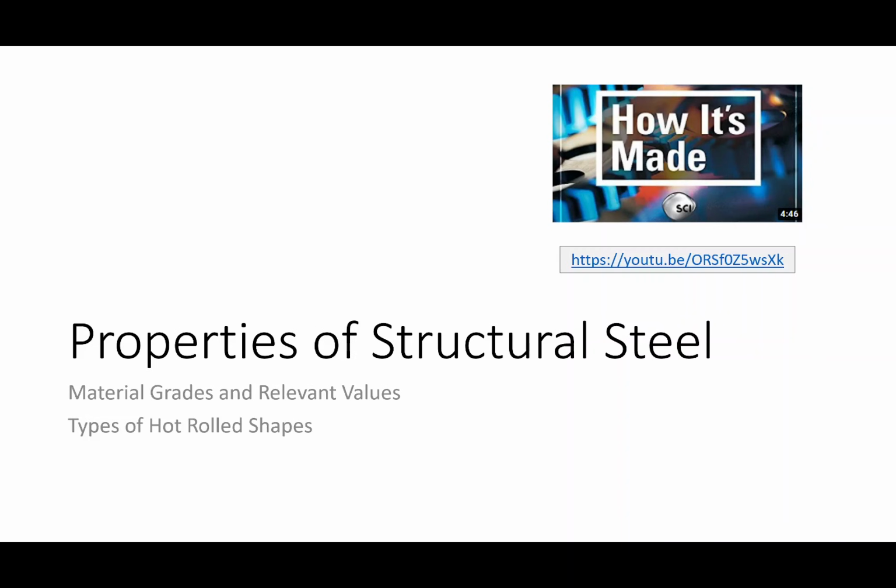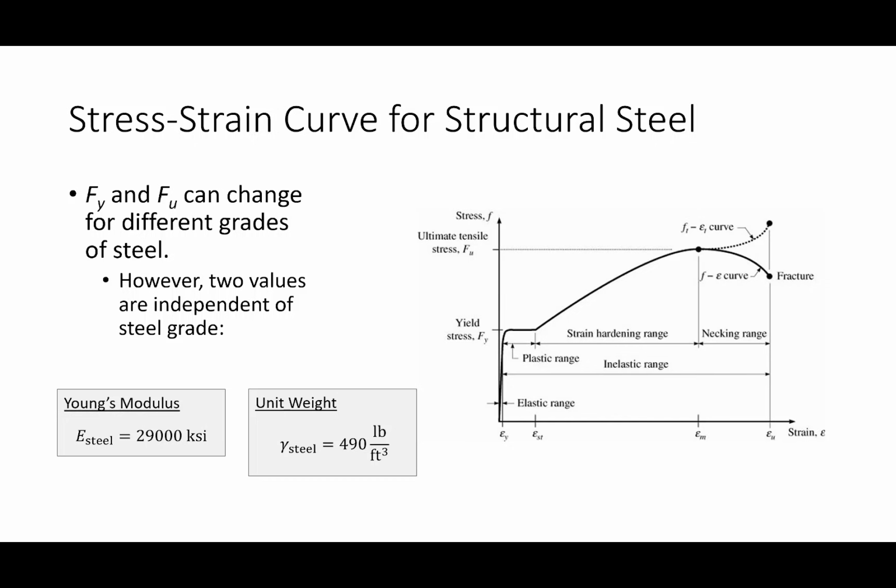Okay, we're not really mining raw iron ore and coal and producing new steel. Really what we're doing is melting and reusing old steel, okay? We're taking scrap, melting it in an electric arc furnace, and once it's molten, we'll draw a sample, check the chemistry, throw in a couple additive elements, maybe some nickel, maybe some vanadium, just to make sure the chemistry's right, and then produce it again. And so I think like 93% of the steel that we produce in the construction sector these days is recycled.